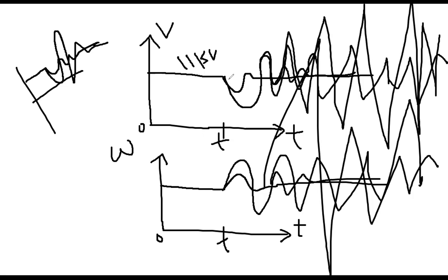I mean, there is no controller that can immediately maintain stability in this situation. It is not possible because every controller needs some time to understand. There is always a time delay and you have to actuate the circuit. That's why it always works in that way. Versus when there is no controller, it is continuously oscillating, and as I said, depending on the network, it might be fully out of step, out of synchronism. So this is the meaning of stability or instability.